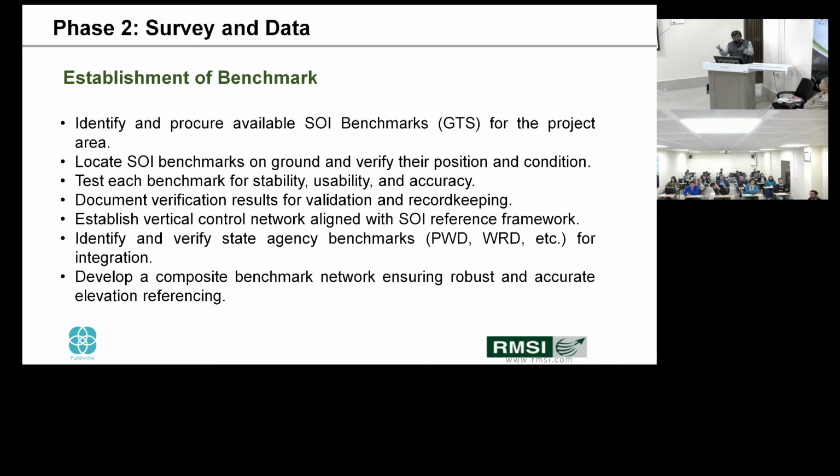I think you know very well about Survey of India benchmarks. They are accurate. They represent the accurate elevation data of the particular site. If you go to any railway station, the bridges or PW offices, irrigation offices, even at the dams, there will be a mark of that, only Z. This is the elevation point of that particular location.